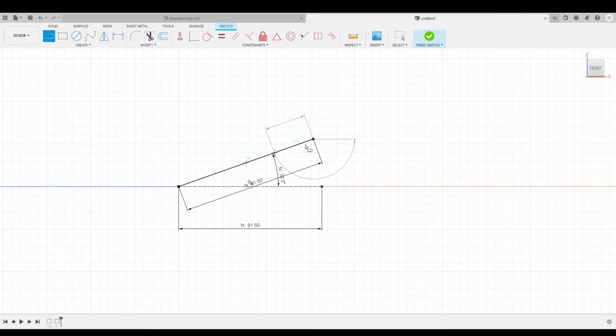Track height. Okay, and then you can notice it's giving me this check mark that's kind of in the way, and I can just keep going instead of having to hit L and do the line again. And that's because I just clicked with the mouse. So you can do that, or you can hit enter and hit L, either way. But sometimes you can inadvertently be creating lines that are not constrained that you didn't realize, and that's kind of annoying when that happens.